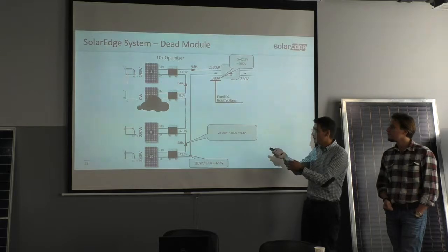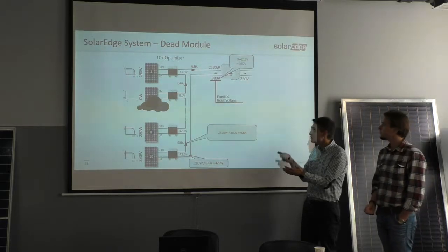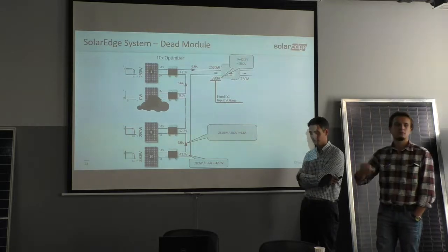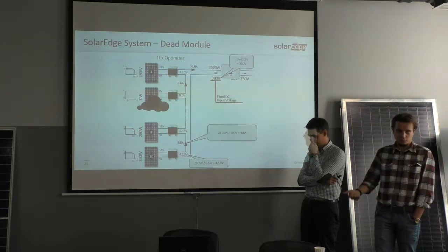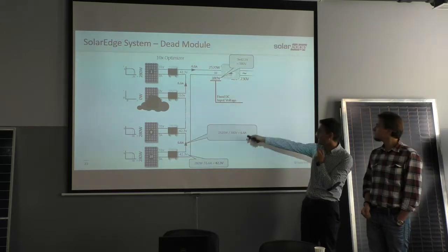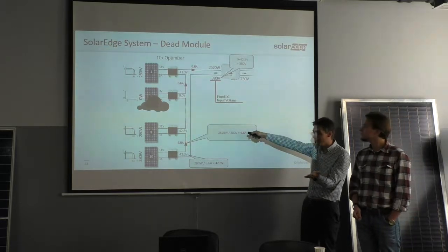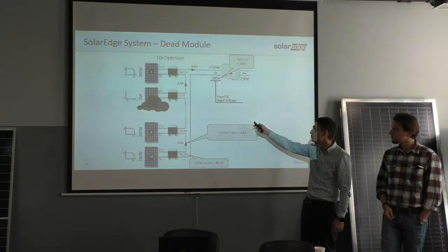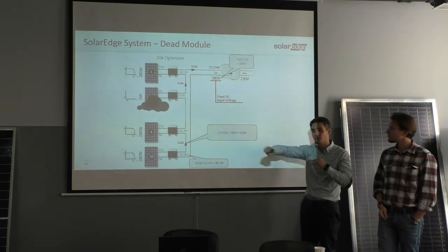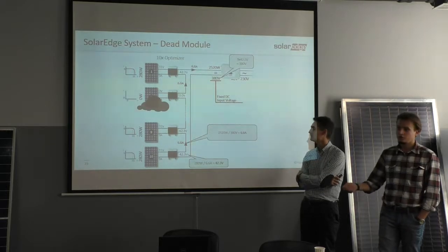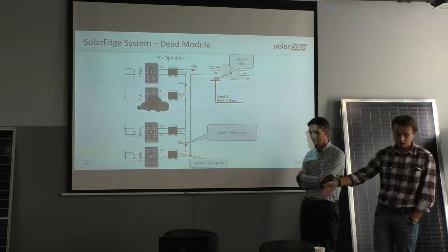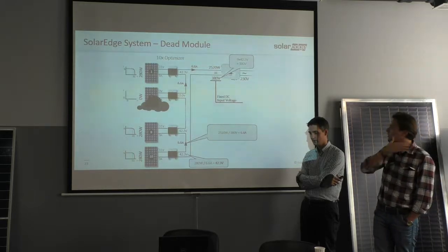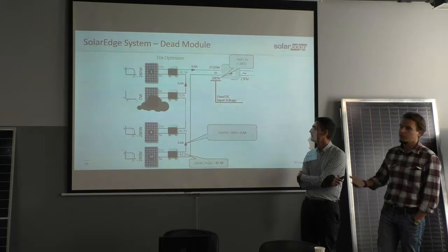So again, we lose one module, and what's changed? Voltage is fixed, so what's changed is the amperes. And because this module is not completely working, the rest, 9, have to adapt to the new situation to keep 380 always at a fixed value. In any case, all the optimizers work, and they compensate for the one module that is disabled, continuing to work with our fixed voltage.